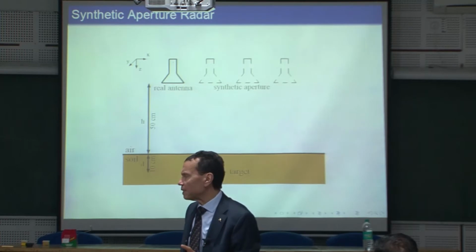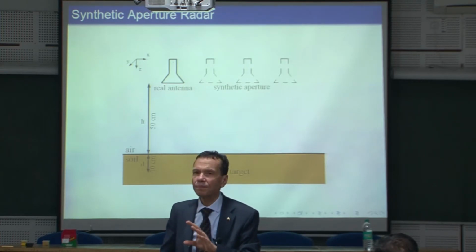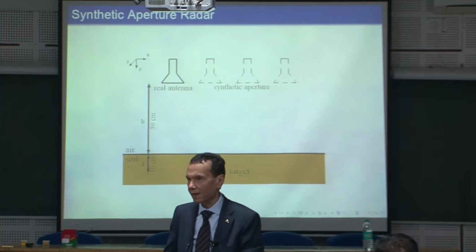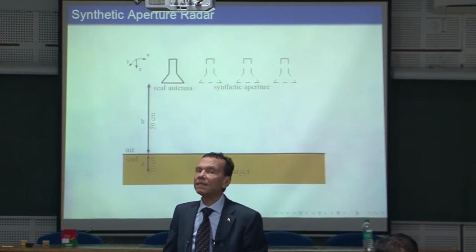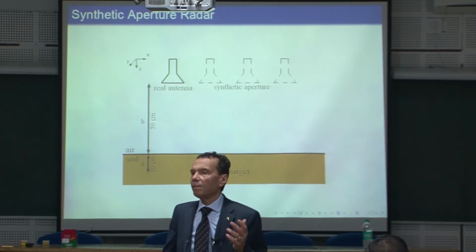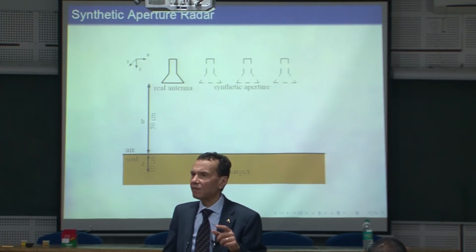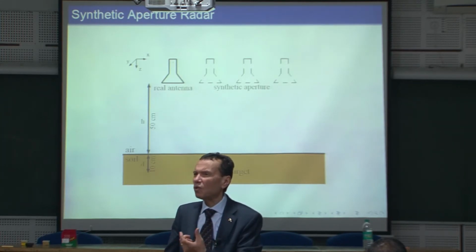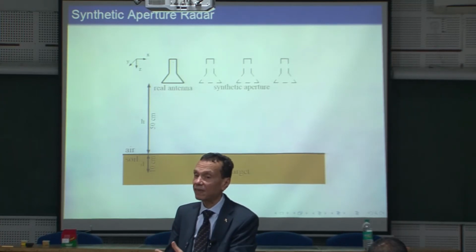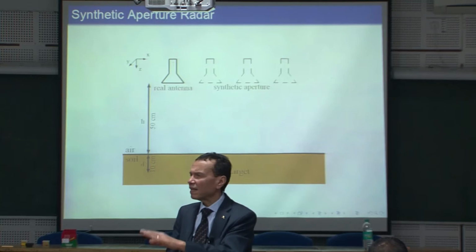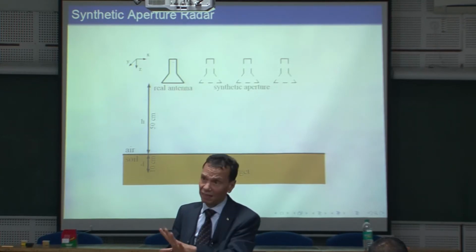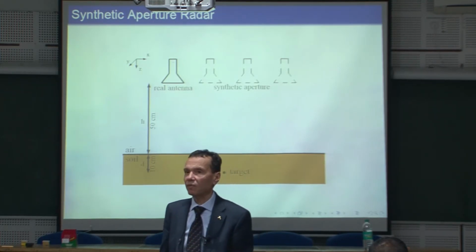I know the free space calibration is really not perfect, like working in a closed environment, but it helps, because at the end, maybe you need the relative magnitude, and over this bandwidth, you hope that the free space effects are flat, whether in the phase or in the magnitude. But you are right; it's really not perfect.